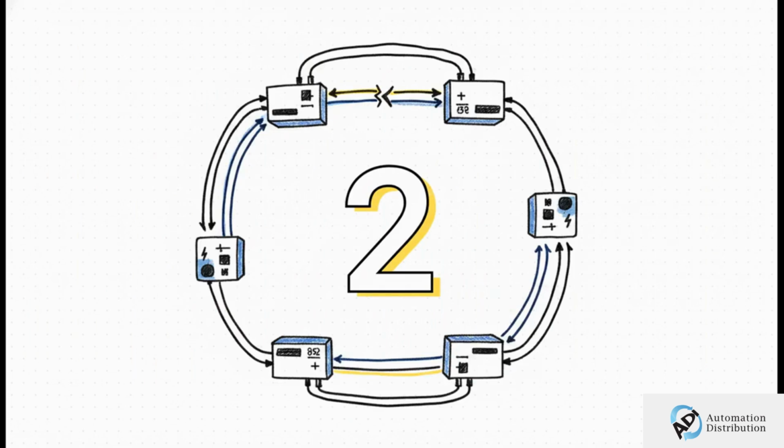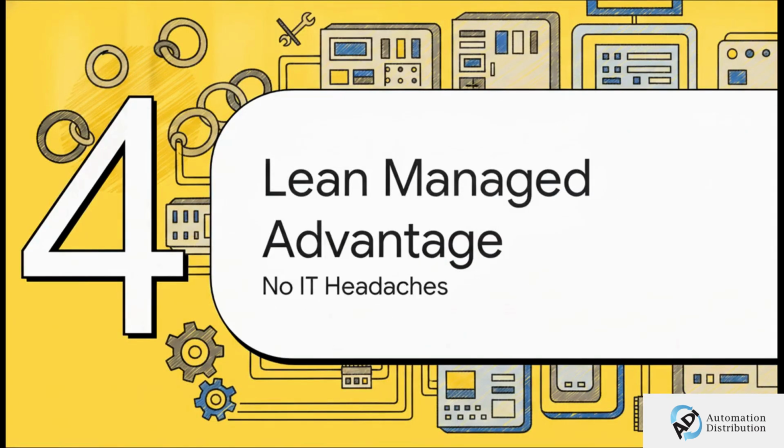You also need hardware reliability, so keep the number 2 in mind here. Backing up both of those protocols at the hardware level, WAGO's 852 managed switches accept 2 independent DC power inputs. This is a total game changer because it means a single power fault won't drop the switch and defeat the entire purpose of your redundancy. You get backup paths for your data and backup paths for your power. Let's move right into Section 4 to see how this becomes an accessible solution.